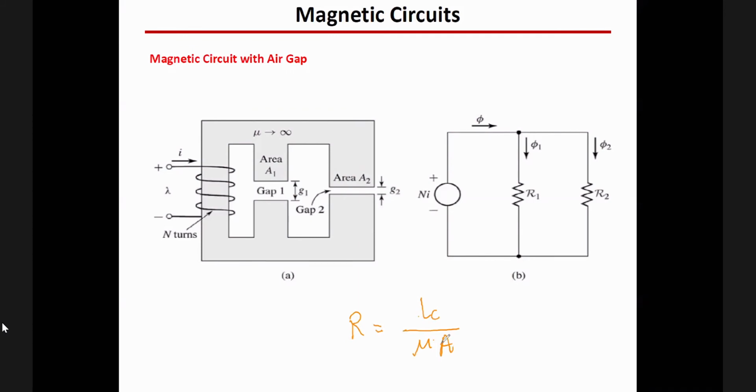When should we say that these three legs should be represented as one reluctance, or when should we first represent this as one reluctance with constant cross-sectional area, and this one as another reluctance? If they have different materials, we're talking about the denominator here, just separate them. If different cross-sectional area, just separate them and combine them later in the representation.